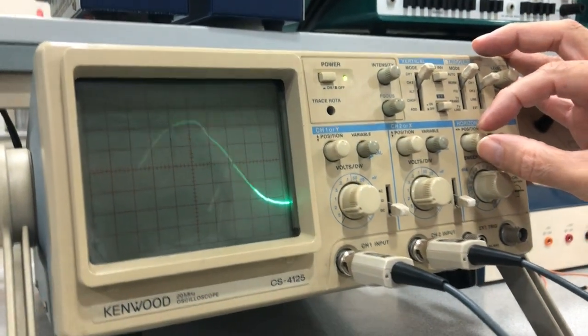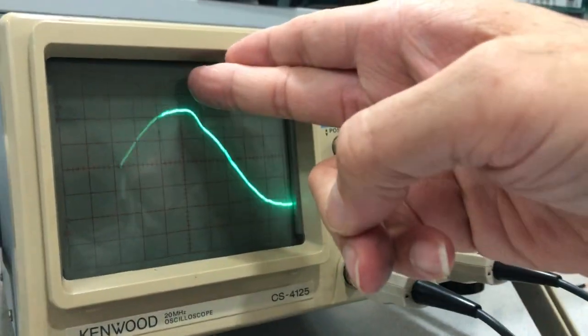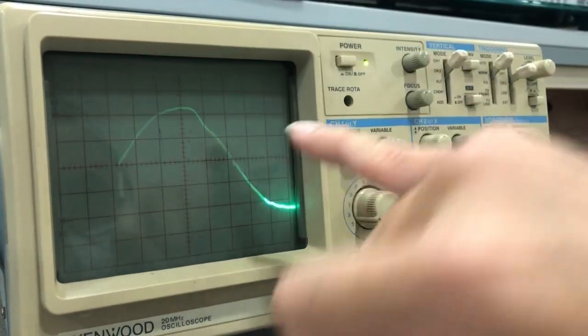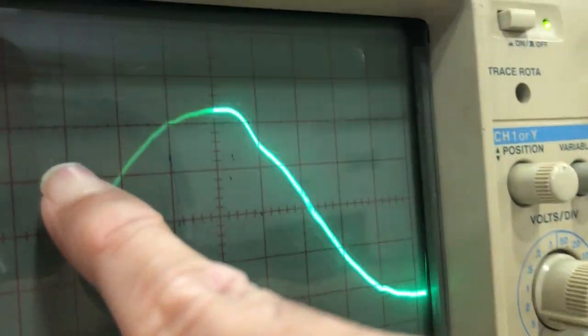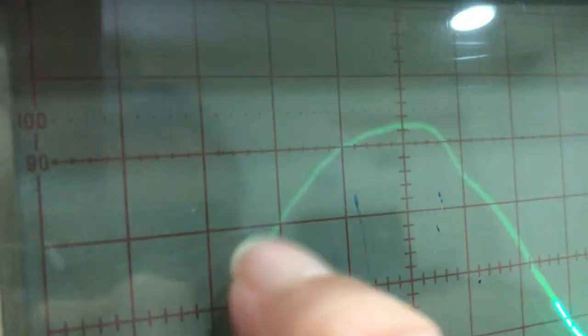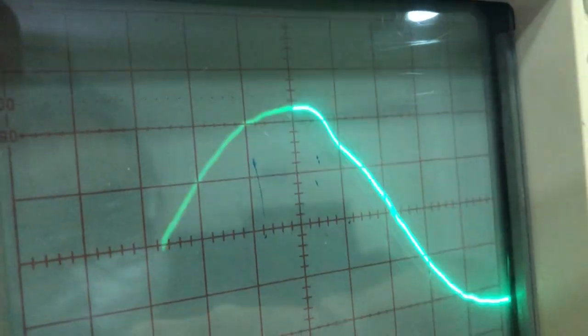Now when I make voltage measurements, I'd like to bring, sorry, my signal peak to this center line, because the subdivisions are drawn there. But the remaining vertical lines don't have these subdivisions that are on this center vertical line.